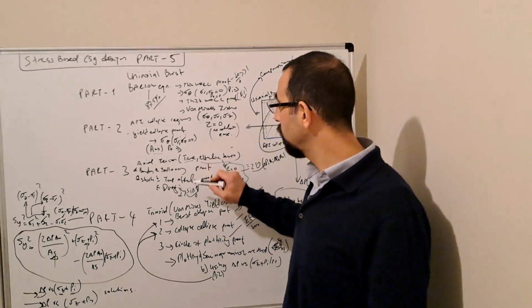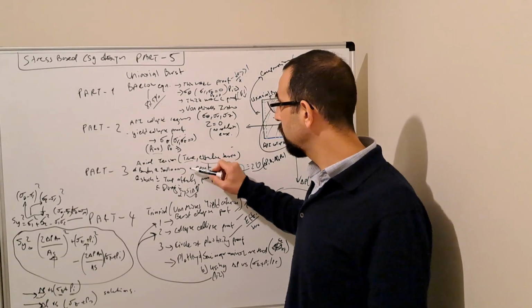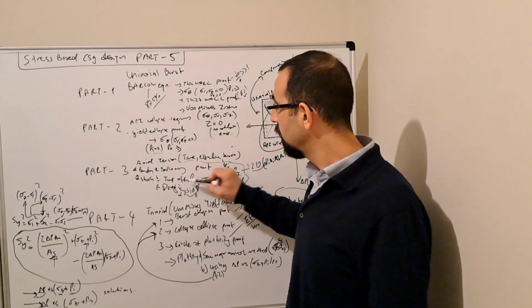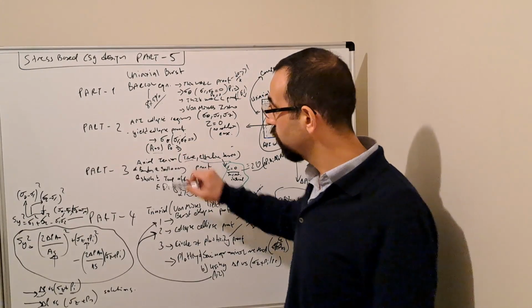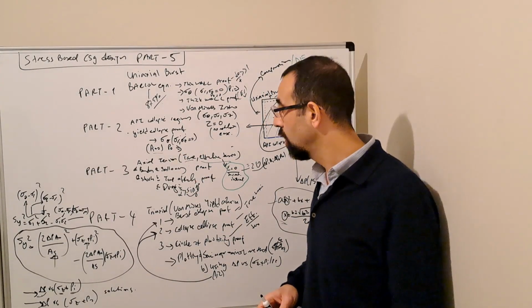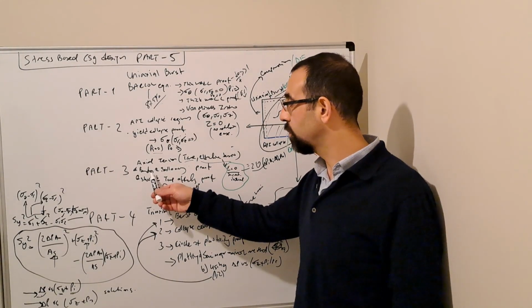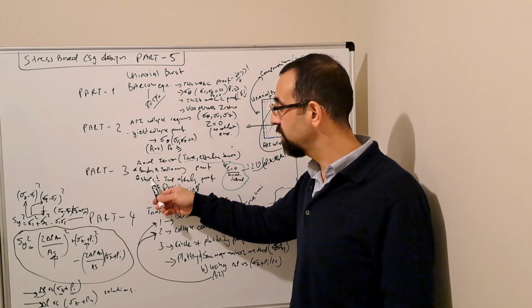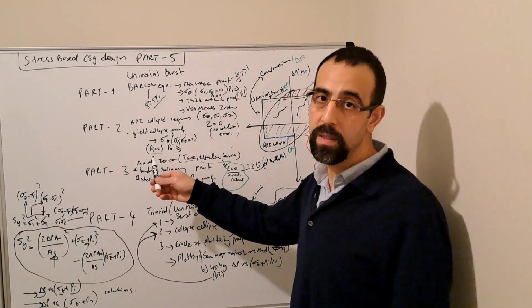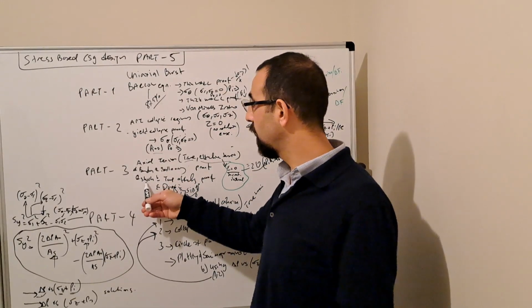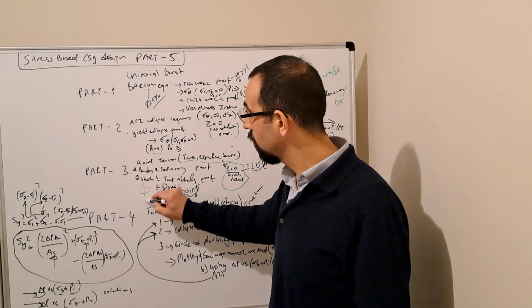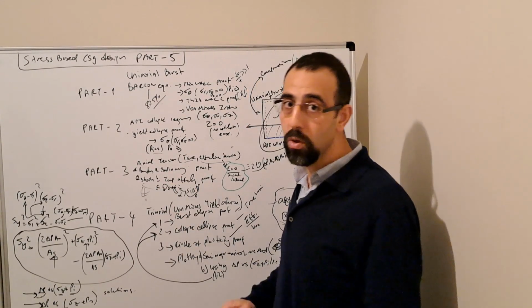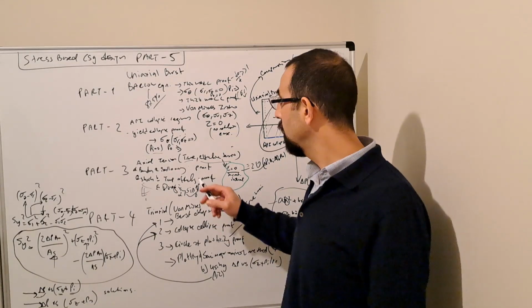So we covered the ballooning forces, and we proved that, then temperature effects and the drag force, and we also showed the proof of the bending and the shock load. Maybe not the proof, but we have shown the concepts of bending, which is mainly dependent on the dog legs, and the shock load, and I mentioned to approach the shock load with precaution.